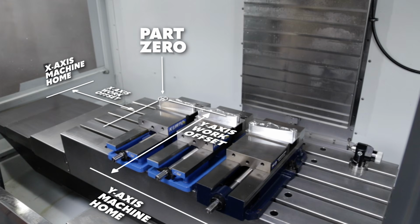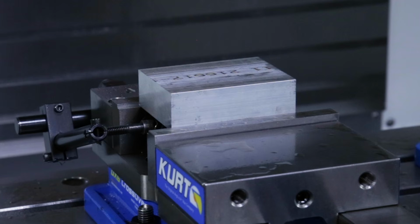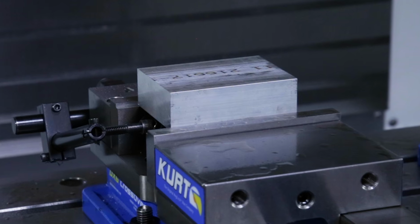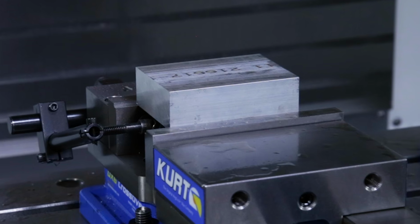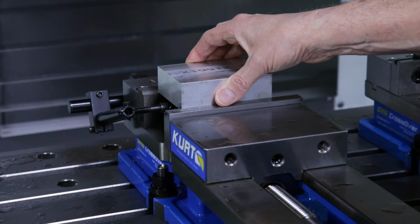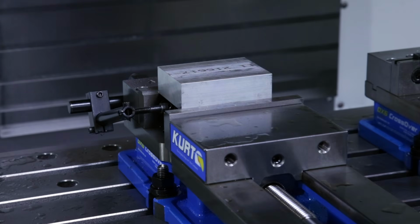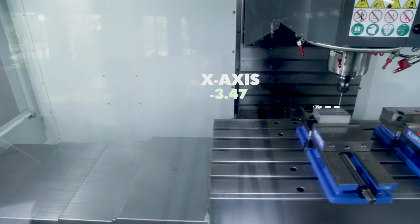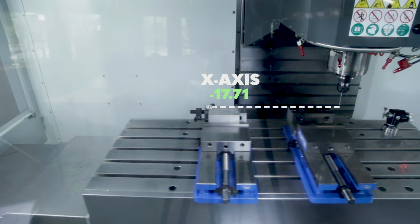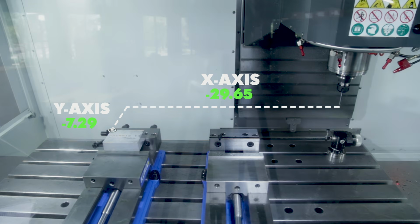Now, let's look inside our machine to get a visual understanding of how these offsets work. Our vise is clamped solidly to the table right here, and the workpiece we'll be cutting is held tightly inside of the vise jaws. In this case, our work coordinate, or work offset as it's usually called, tells the machine that this left rear corner is exactly minus 29.65 inches away from home on the x-axis and exactly minus 7.29 inches from home on the y-axis.